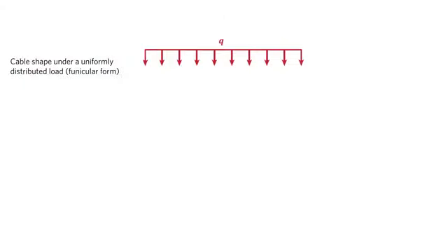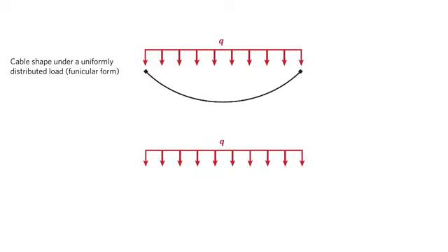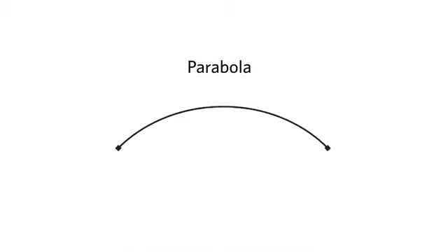The 2D behavior of an arch is not the same as the 3D response of a vault, but it will help us to move our thoughts in that direction. What is the ideal form for a concrete arch? Well, if we hang weights from a string, we get pure tension in that string. If we can freeze it and turn it over, we get pure compression, which is perfect for concrete because concrete has almost no strength in tension. If the load is uniform, the shape is essentially a parabola.